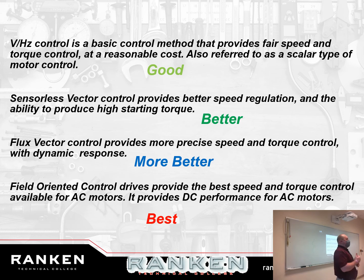It just goes by how much torque or how much force is being applied to the motor. All right? Flux vector provides more precise speed and torque control because it has a dynamic response. It actually has some sort of feedback device or some sort of way of monitoring how fast it's going or how much output it's getting.